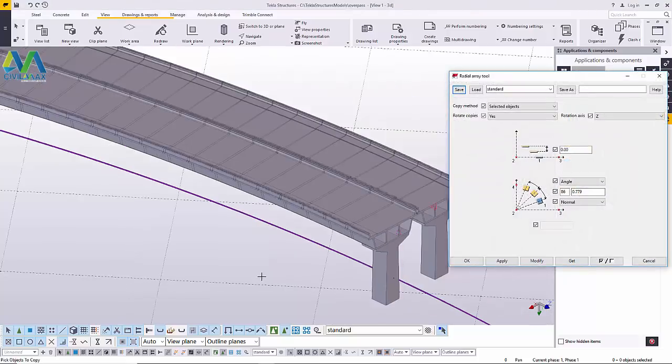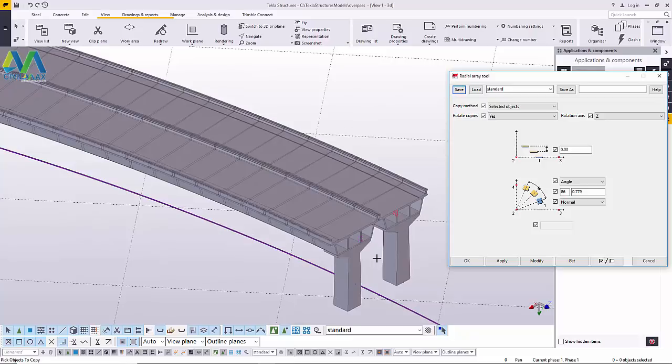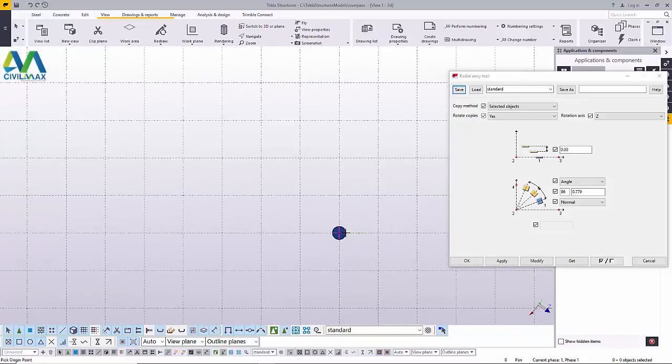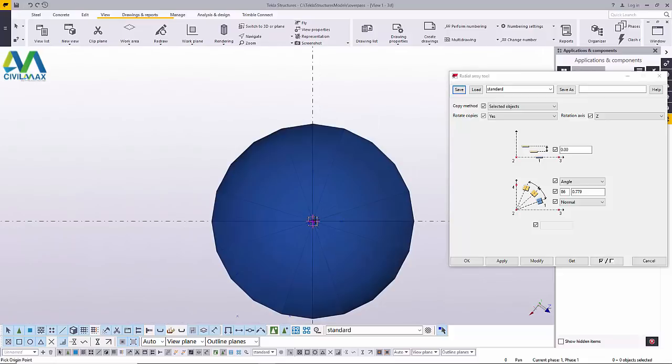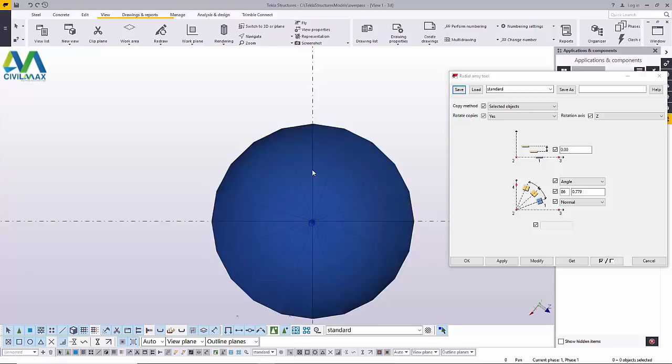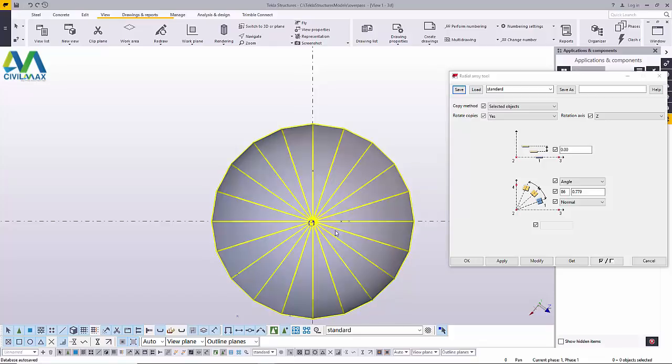I'll double click on it. Now I'll come here and pick on the pillars that I want to populate along the path that the shells have followed. Now I'll pick on the columns here. I'll press Ctrl while picking these pillars. I'll pick on that. Then I'll press my middle button on the mouse, then switch back to plan view and come all the way to this end, and I'll snap at the midpoint right there and select my X direction and define my Y direction and press my middle button on the mouse.